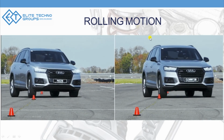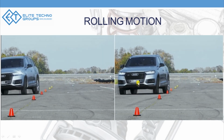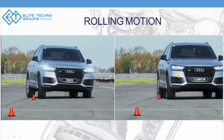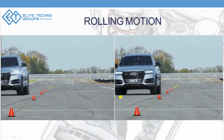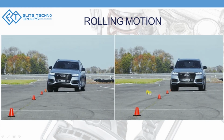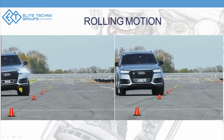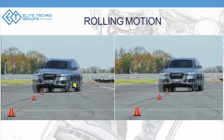Now on the right-hand side, there is no compression. There is no movement of the body when it turns, compared to the left-hand side. So the right doesn't have a rolling motion on the car, but the left has a rolling motion. That theta change, the body compression that you can see, is what we call rolling motion.